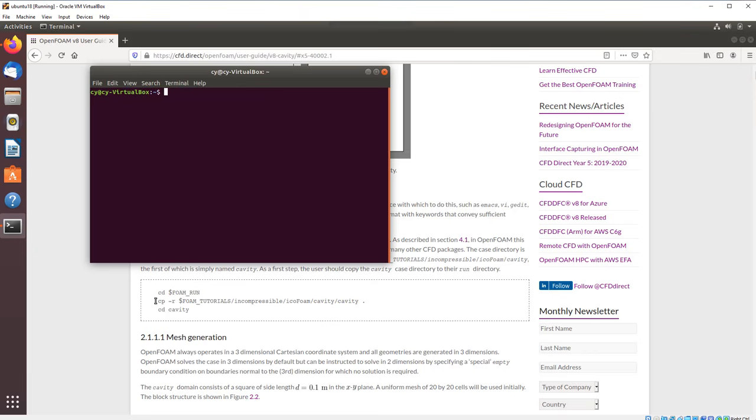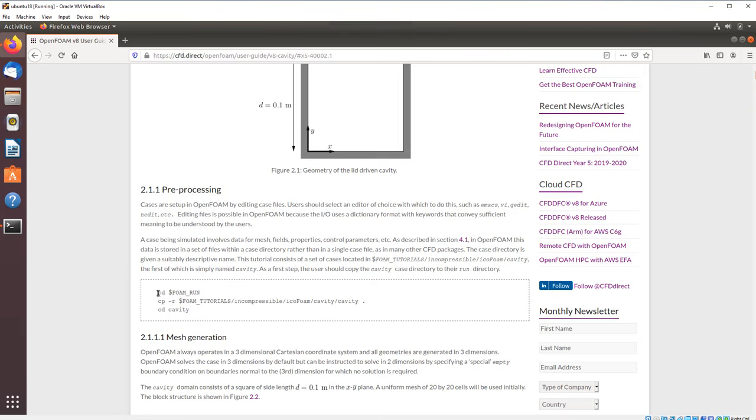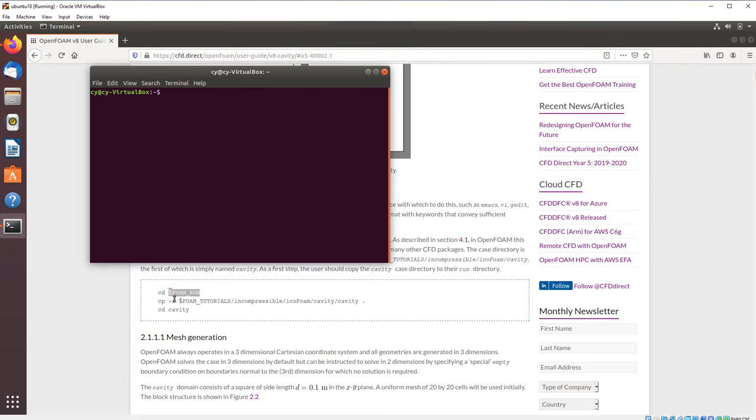First, if you have installed OpenFOAM, like I mentioned in my previous installation video, you should have this FOAM_RUN variable in your bashrc. If I do an echo and paste this, you'll see that the content of this variable is actually this path on my computer. So when you say cd $FOAM_RUN, it means please go into this folder. That's where my OpenFOAM tutorial will be copied.